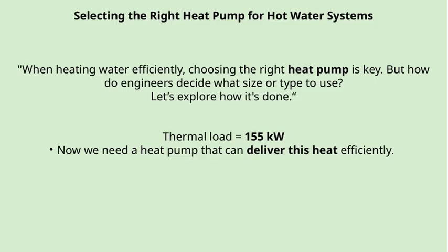Once we know the thermal load, our goal is to find a heat pump that can deliver this amount of heat efficiently and reliably. It's not just about matching the capacity, it's also about ensuring the system operates at optimal efficiency, which helps save energy and reduces costs. This decision-making process is a key part of designing sustainable and effective hot water systems, connecting directly to the overall goal of maximizing energy efficiency in building management. So, selecting the right size isn't just a technical detail.